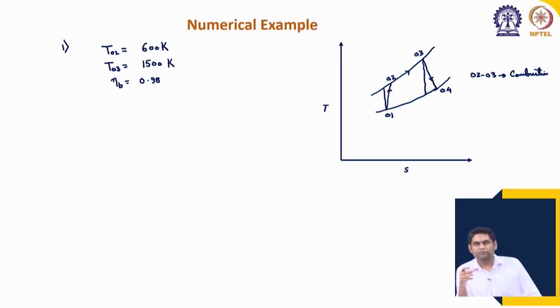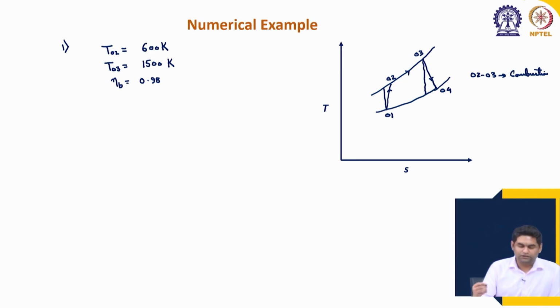In these cases, because we are using a very lean mixture and the process is occurring in steady flow condition, the combustion occurs almost fully, and we get around 98 to 99% of the theoretical energy release. The calorific value of the fuel is given as 40 megajoule per kg. So, all are realistic values.